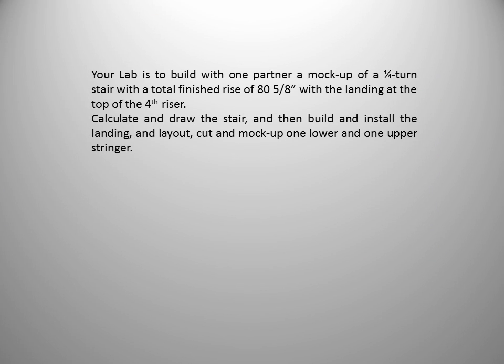Your lab is to build with a partner a mock-up of a quarter-turn stair with a total finished rise of 80 5/8 inches, with a landing at the top of the 4th riser. Calculate and draw the stair, and then build and install the landing, and lay out, cut, and mock up one lower and one upper stringer.